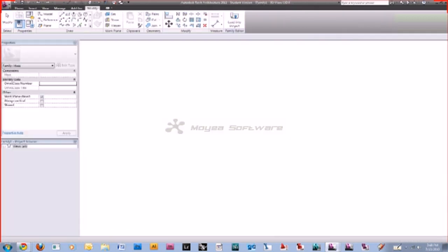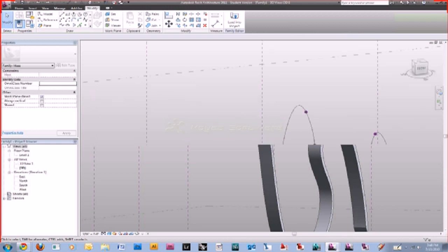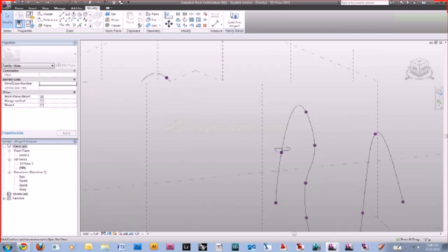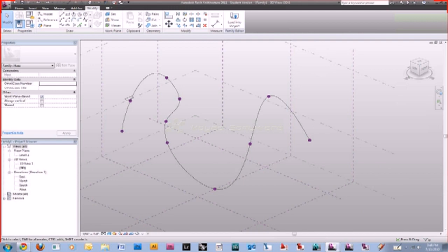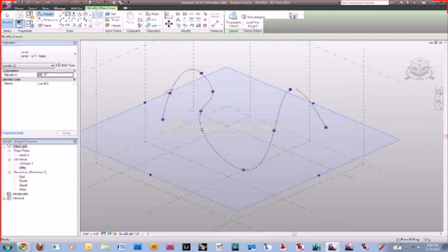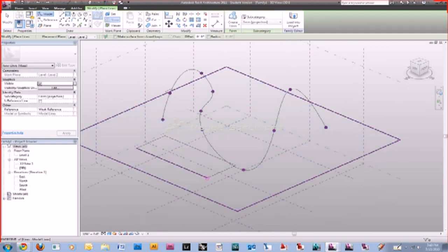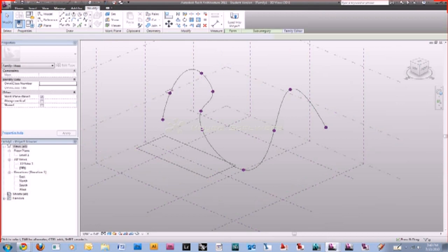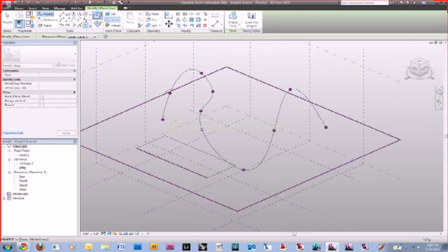He was editing those faces. Now, before we go on, in case you made a shape that didn't have any points already on it, like say it was a rectangle, let me select this reference plane. Let's say we had a rectangle that we made for our path. Now, to do a sweep around this, you'd have to select a reference point, which we talked about earlier, here. And then you're going to take that point and place that one on the shape.